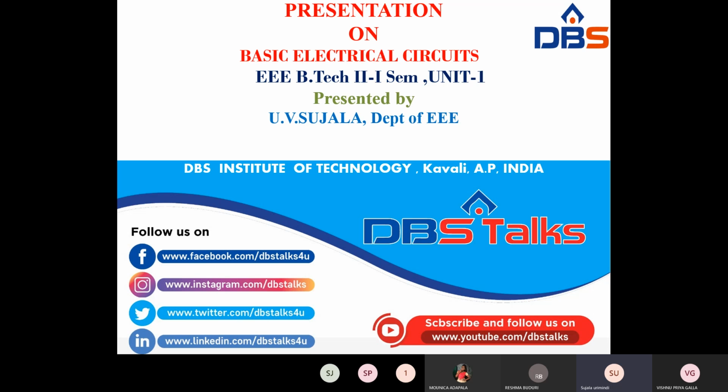Next here, plus to minus, minus V2, simply because it is a voltage. And here, plus to minus, minus I into R3. Next here, plus to minus, minus I into R4. Next here, minus to plus, so it will be the rise of potential and it will be plus V3. Next here, I tell that this is positive, this is negative. Plus to minus, minus I into R5. Suppose it is minus to plus, then plus I into R5.